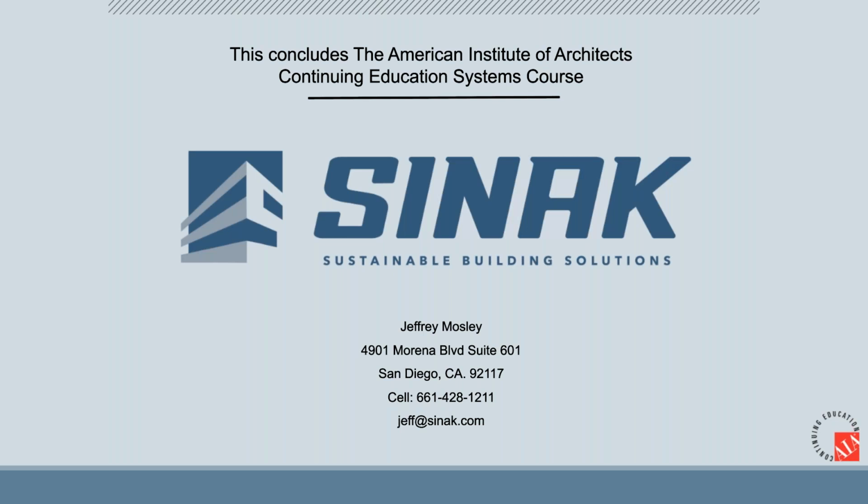Now, we have developed at Sinak a best practices policy of experience through different geographies around the country that have harsh environments. One of the things that we found on robotic industrial applications, where we're doing places like Tesla or IKEA warehouses that have robot systems in them, which have a very, very flat tolerance requirement, is that at 48 to 72 hours after placement, you can come back and reapply to the joints. By then, the joints have cracked, they've opened up, and now not only have you addressed the top and the edges and the bottom and the first inch of saw cut, now you're actually going all the way down to the membrane and controlling the entire joint wall. That's going to reduce your curling or eliminate it completely. And in doing that, you have a lot less cost associated with doing grinding and leveling after the fact so that you can meet those high tolerances.